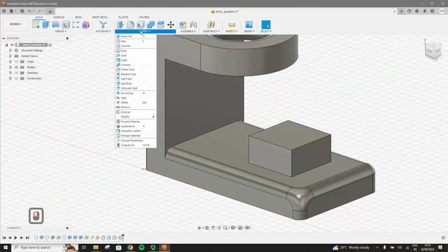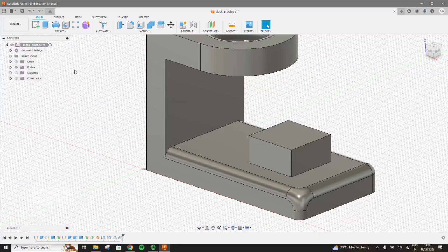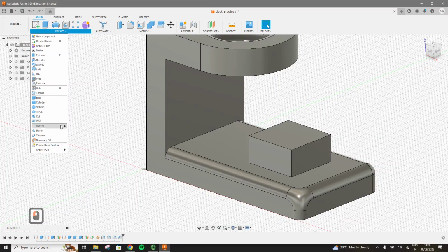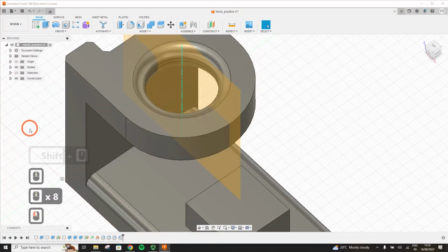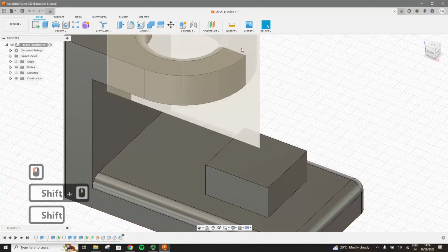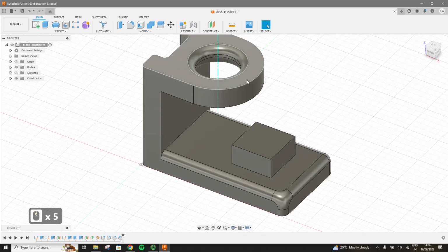What we can try now, and that is something that you are going to use quite a bit if you are working with nuts and bolts and integrating some joineries in your design, is making patterns. A pattern is essentially any feature that you create, but you want to create multiple of those. For that, you remember we made an axis for this, right? So let's hide the plane, but keep the axis as it is. We'll try to make some holes on this surface around this axis, okay?